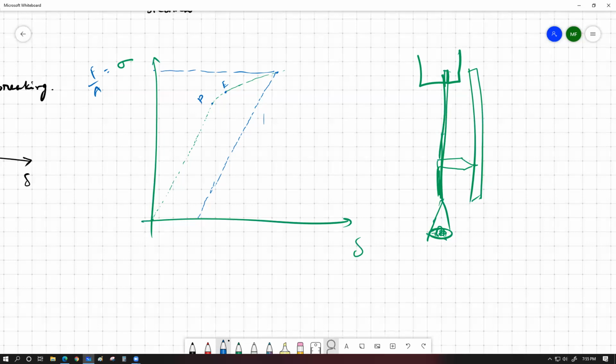So whenever we start to unload the object, it will essentially maintain the same Young's modulus. That's why the object comes back following a line parallel to the original linear part of the graph. And eventually, when we remove all the load, the stress value drops all the way down to zero. That's when the object hits the bottom line and is not deformed any further, because you are no longer applying any force, and the amount of permanent deformation can be found by the x-axis intercept.